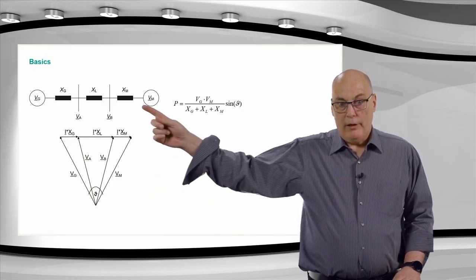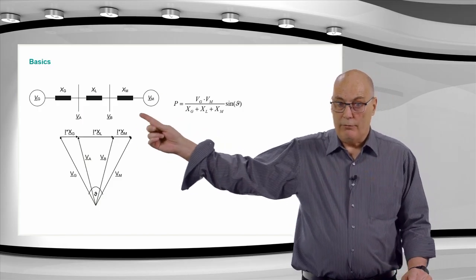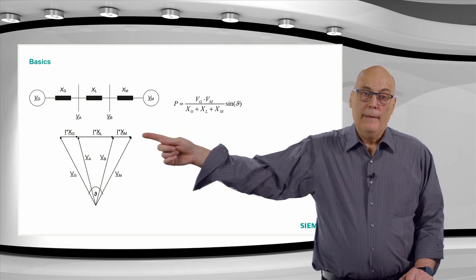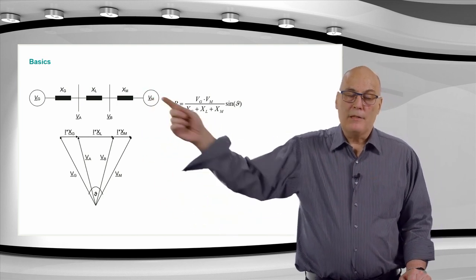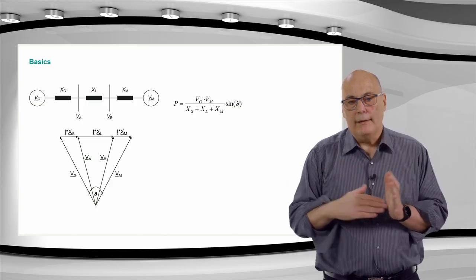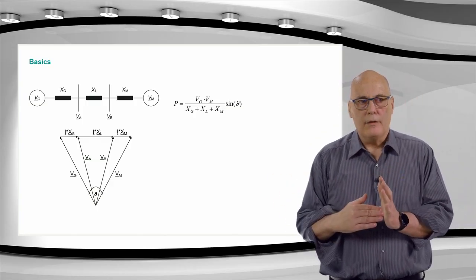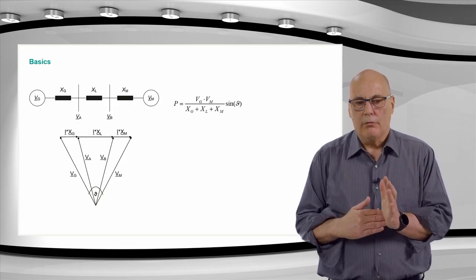And the current would flow left to right. There's only one current in this system. There's no other shunts. It's flowing from the generator to the motor. That's the current, and this is the current shown here. And because that current is vertical, in these reactances it causes a voltage drop, which is 90 degrees. Current in a reactance is going to be leading the voltage. That's right.